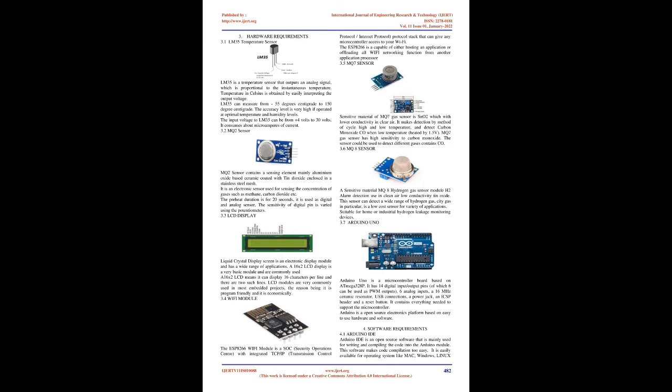3. Hardware requirements. 3.1 LM35 Temperature Sensor. LM35 is a temperature sensor that outputs an analog signal, which is proportional to the instantaneous temperature. Temperature in Celsius is obtained by easily interpreting the output voltage. LM35 can measure from minus 55 degrees centigrade to 150 degrees centigrade.